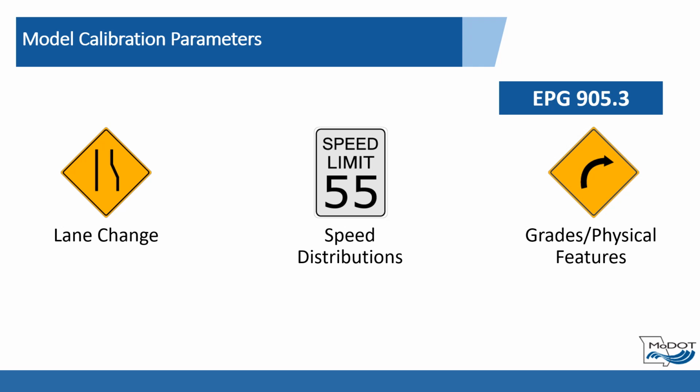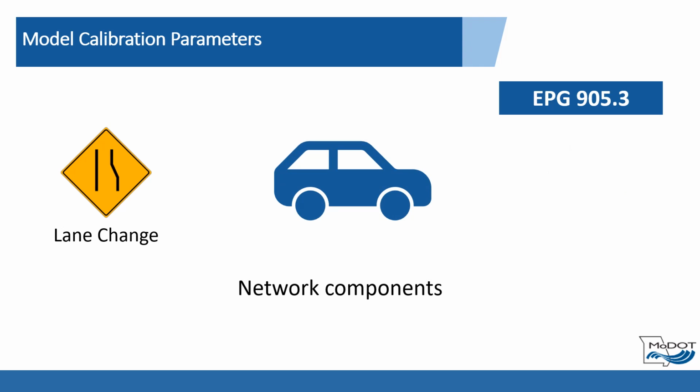Adjustments to conflict areas and priority rules can have similar effects of aggressive or passive behavior at stop or yield-controlled junctions. Finally, network components, such as link gradient, can be modified to affect acceleration characteristics, particularly of large vehicles. In general, these network element parameter changes, which include the lane change distance adjustments discussed previously, should be adjusted first before attempting more global changes to driver behavior parameters.